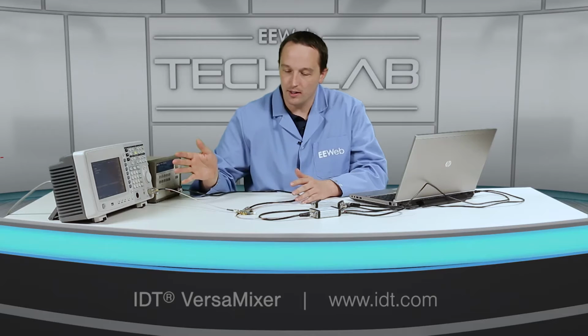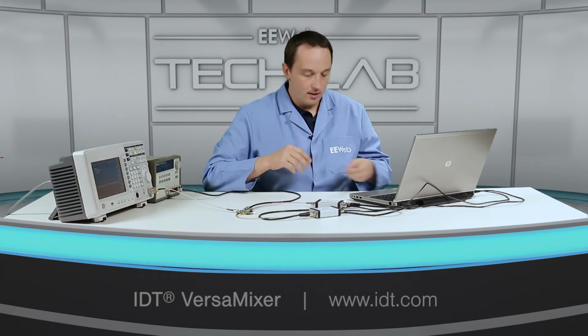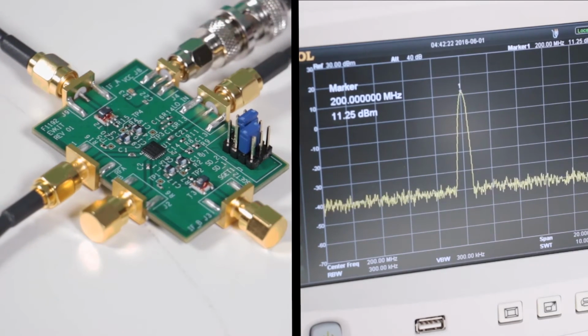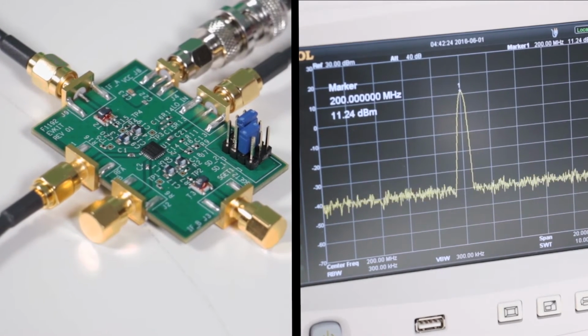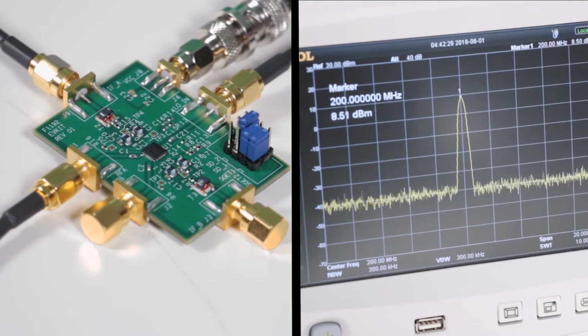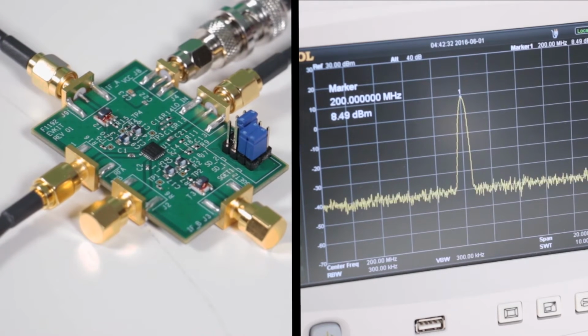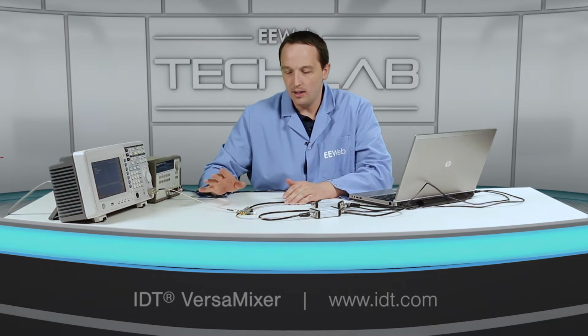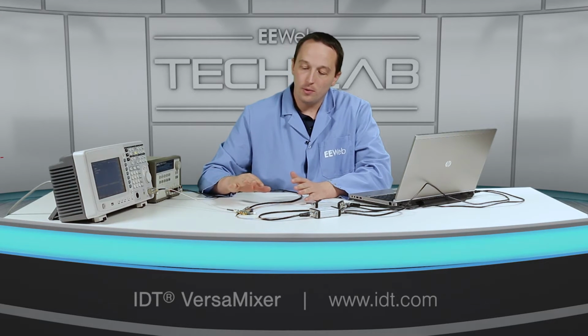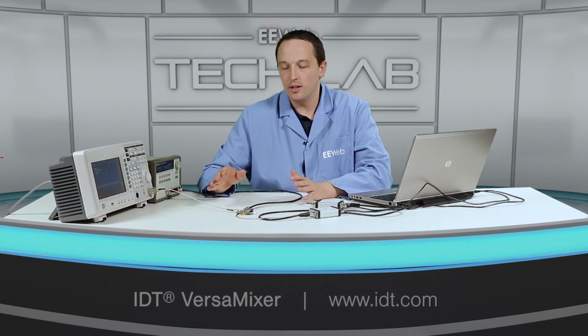Now, what's not apparent on here is if we change the gain, and we can do that by shorting some of these pins together. If we go ahead and reduce this gain, what you don't see is that noise figure stays very, very flat. So even though we dropped the gain from about 11 dB to, I think the minimum setting is 2 dB, the flat noise technology that IDT has developed keeps that noise figure very flat. And also the zero distortion technology maintains that very, very low third order intermodulation distortion.